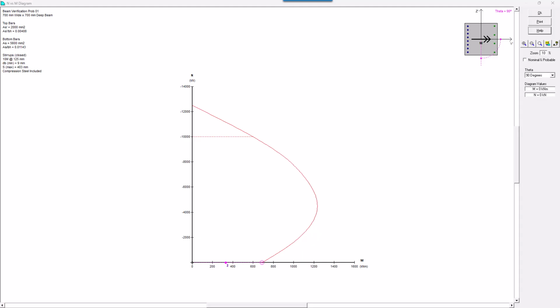Now in this scenario, I might be interested in understanding which beams, or which bars rather, are going into tension or compression, as it may not necessarily be as cut and dry as if I had bending about the z-axis here, as you can see. So you can imagine if I had bending about the other axis, it would be pretty clear that either the top or bottom bars are all in compression or tension. However, it's not so cut and dry in this scenario.